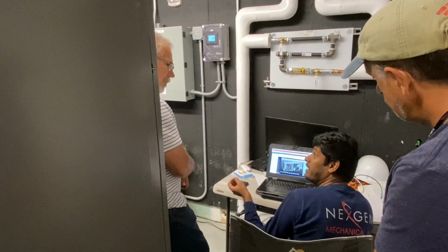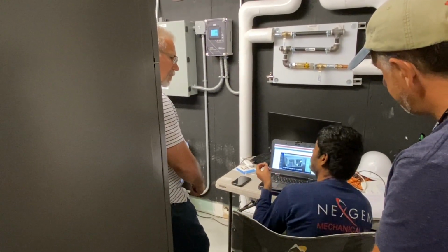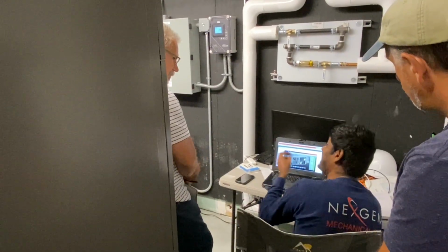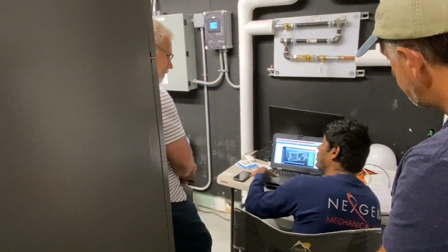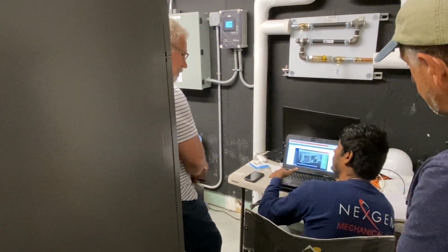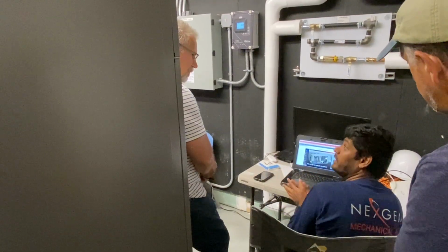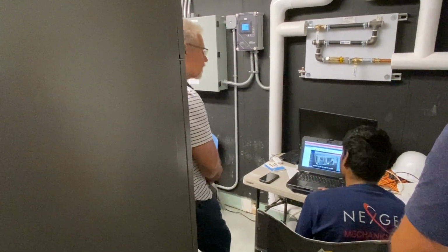There is an outlier in the average calculation. So from the user interface, you should be able to unselect that VAV so that it doesn't go through the dynamic DP calculation, so that you don't skew the pressure set point. You will have that ability in the user interface.